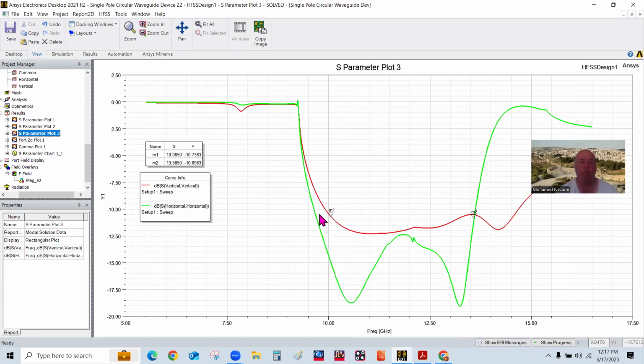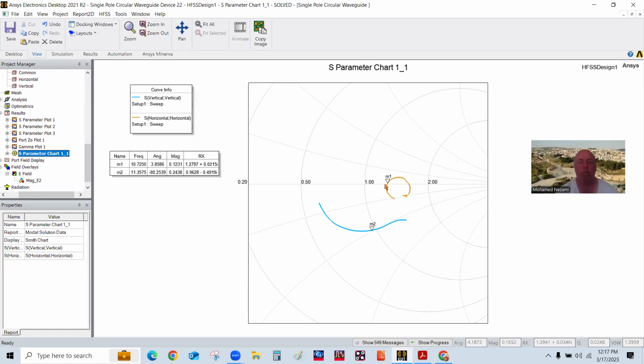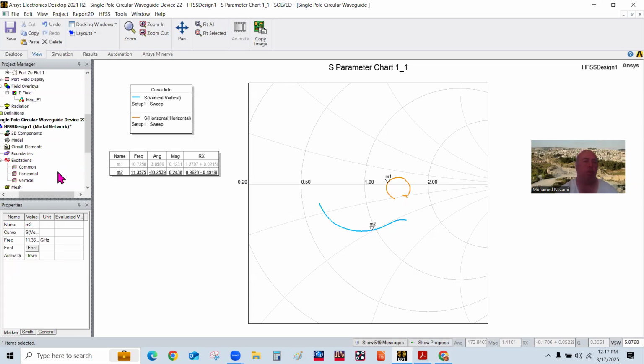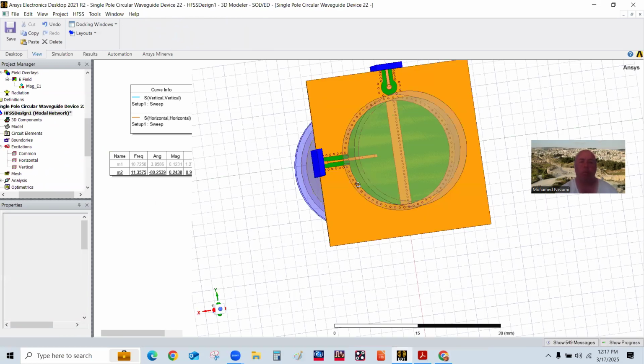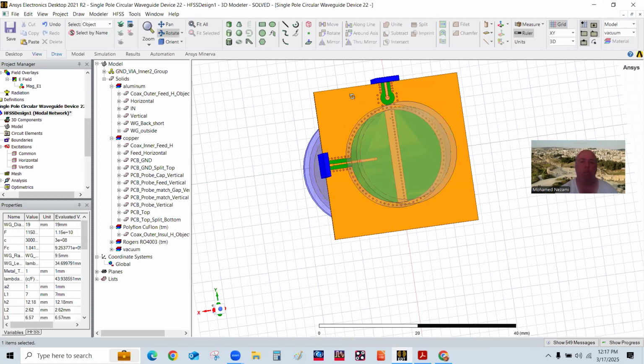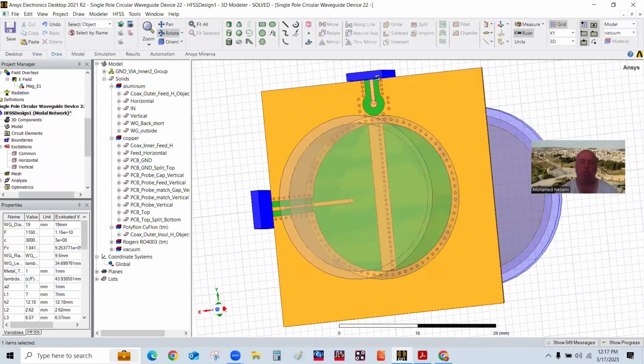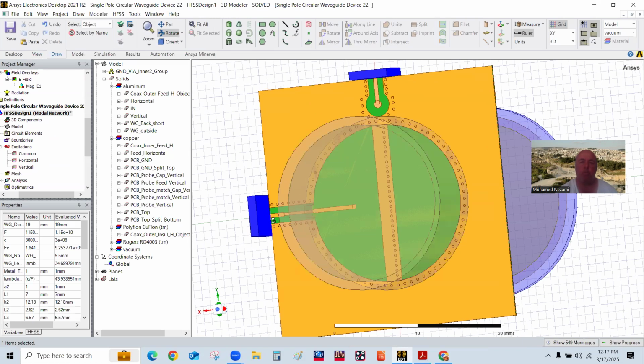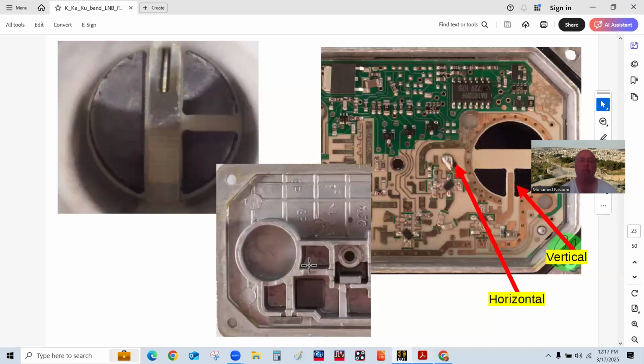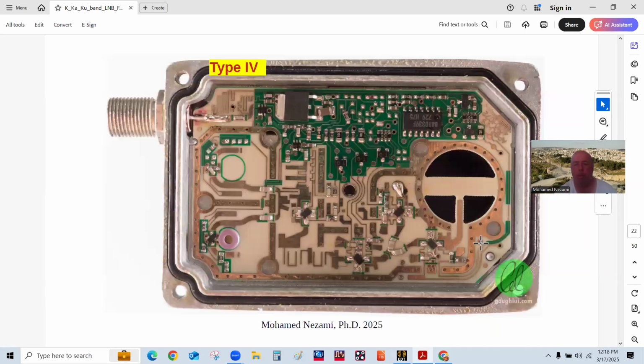This return loss here becomes very important because I put this on a Smith chart. These impedances that you can see here are what is going to drive the LNA device. Even though in this case, for testing and evaluation purposes, I put it to the side of the board using microstrip line, in actuality these don't go like this. Let me go to a clearer one.